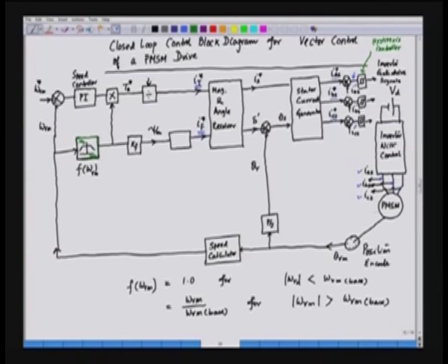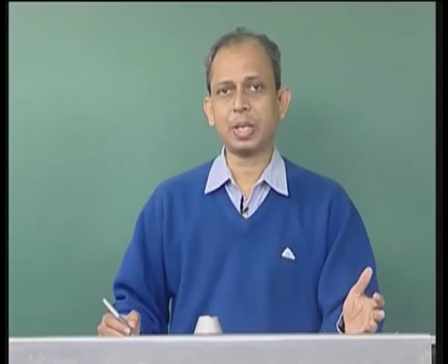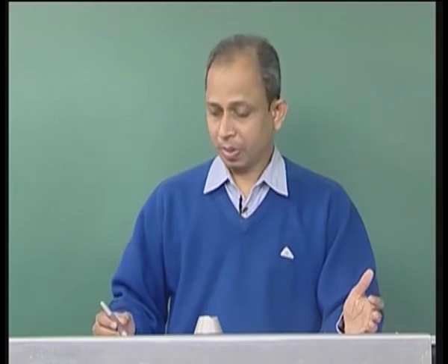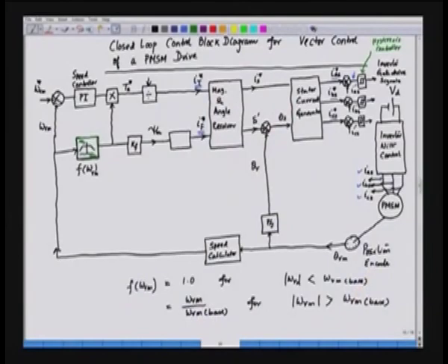The inverter here is a 3-phase inverter having 6 IGBTs or 6 transistors, and this inverter is feeding the 3 phases of the PMSM drive. The hysteresis controller generates the gate drive signals of this inverter, and the inverter drives the current into the stator of the permanent magnet synchronous motor for the control.